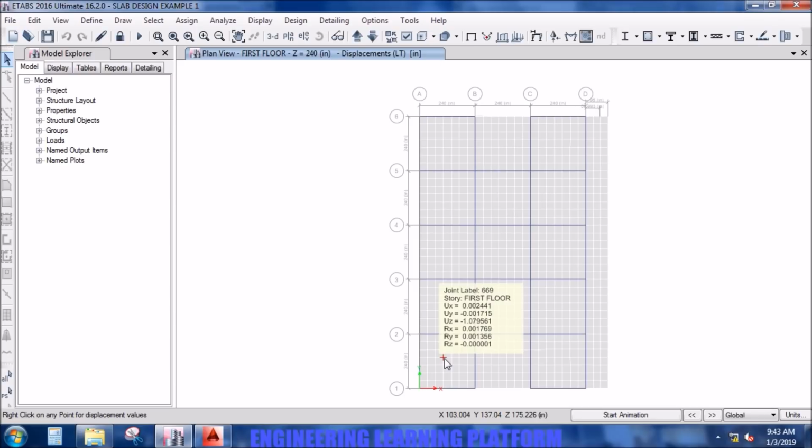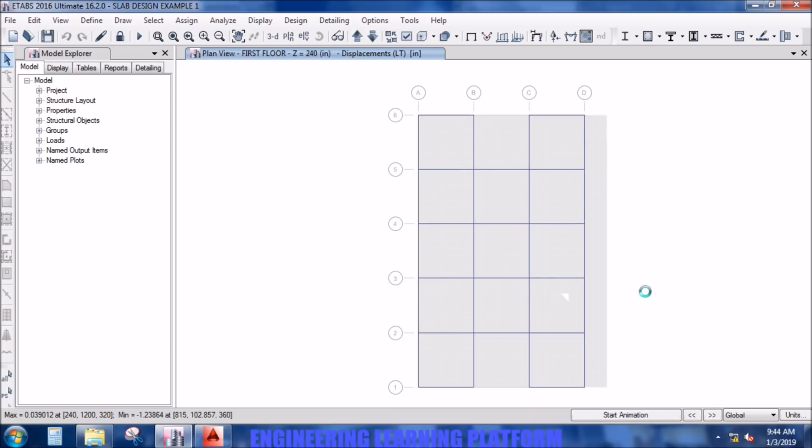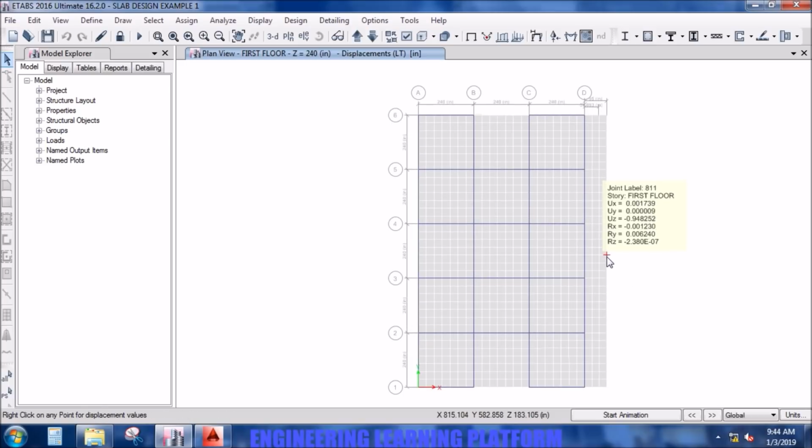The structure was simple here so that I know the deflection will be maximum due to positive moment in the mid spans, as it is uniformly supported from all the directions by beams. So in particular spans, the deflection is higher than 1 inch, like this one span. So I may ignore the 0.006 inches exceeding the limit, which is very less. Here the limit was exceeded by 0.15 inches as the limit is 1 inch.